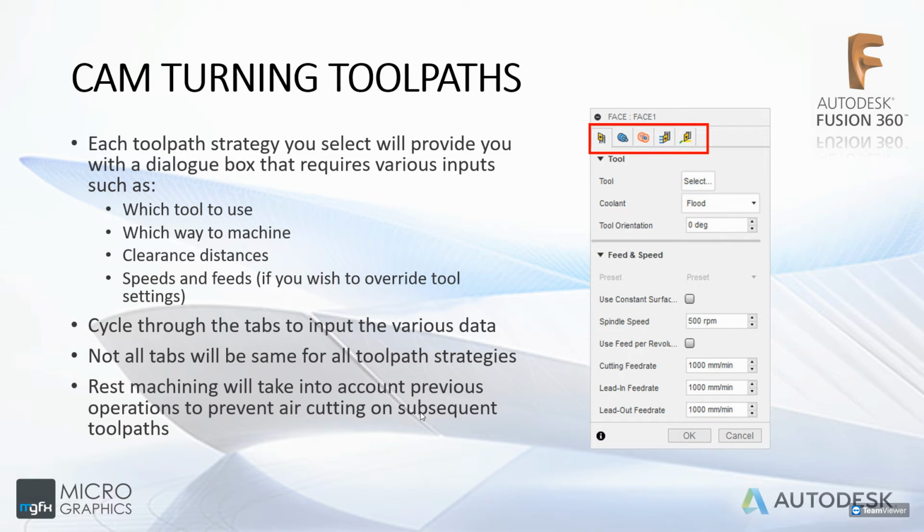Generally, the manufacturer of that tool would give you a rough idea of how capable it is and what are safe operating speeds. However, you can override these settings per operation. So if you're doing a facing operation and you know this tool can handle a much higher speed to go and face off really quickly, you can override it in this toolpath generation menu.